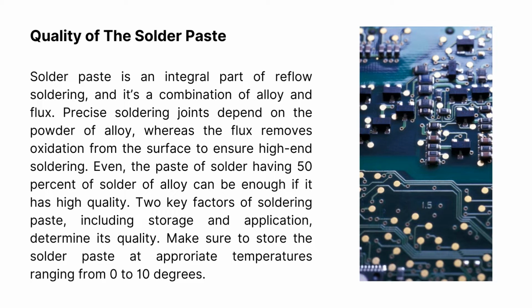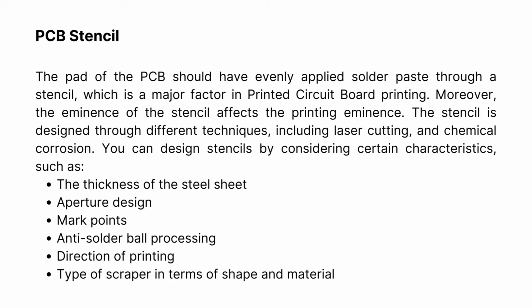Two key factors of soldering paste, including storage and application, determine its quality. Make sure to store the solder paste at appropriate temperatures ranging from 0 to 10 degrees. PCB stencil. The pad of the PCB should have evenly applied solder paste through a stencil, which is a major factor in printed circuit board printing. Moreover, the quality of the stencil affects the printing quality.